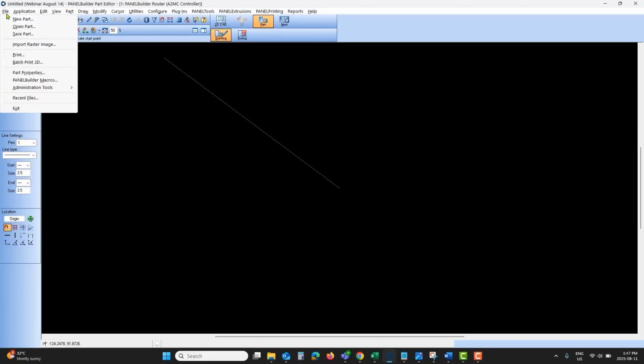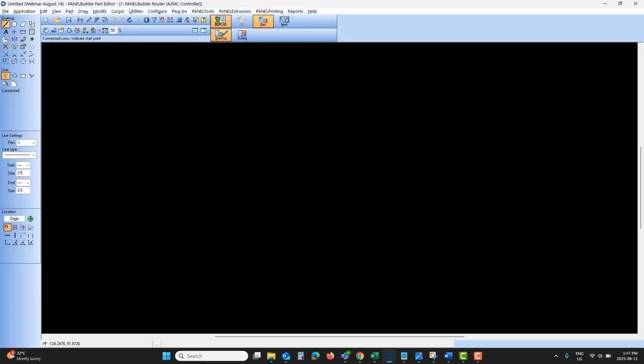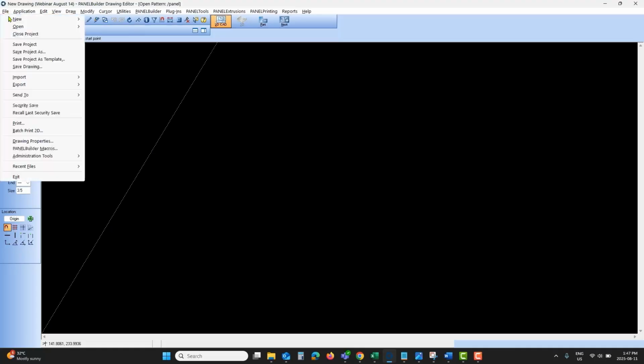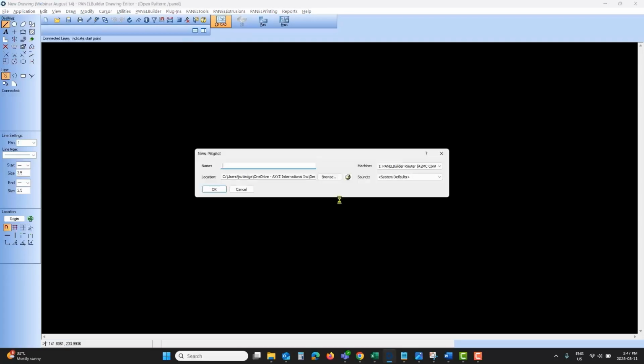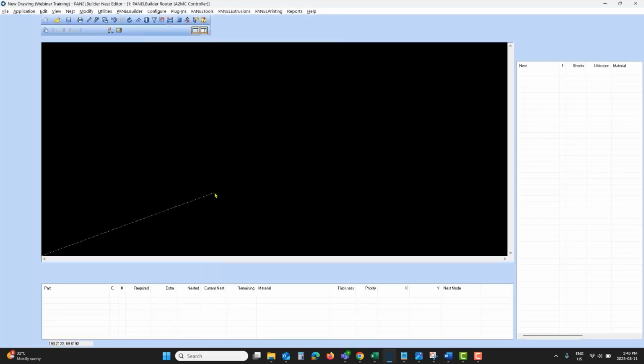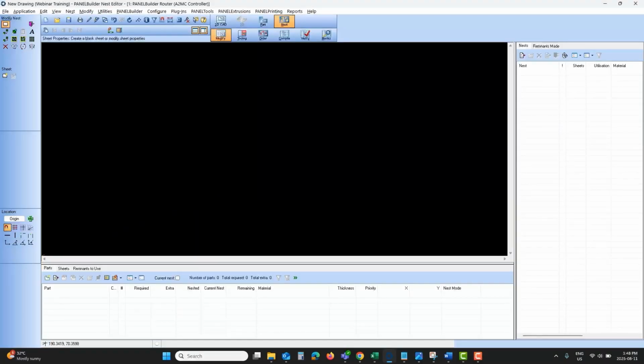We're going to go into File, make sure we're in 2D CAD, File, and New Project. We're going to hit No there because there's nothing we need to save. And we're going to call this project Webinar Training for today, and hit OK. And we have now created our project in PANELBuilder.